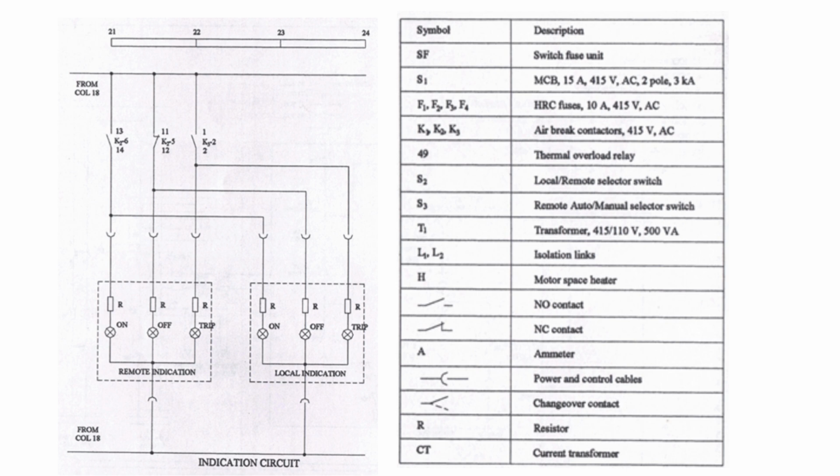Similarly, if I say find contactor K2-6, it could be difficult. But when I say find contactor K2-6 in column 21, since it is located on page 2, it's easy to find, right? So the second thing that is clear is the column number and the page number.